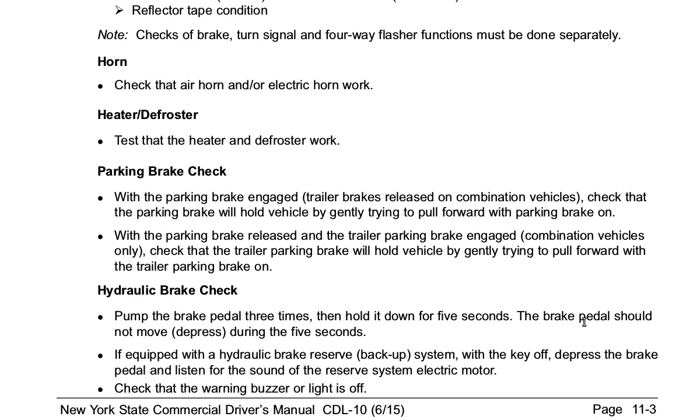Parking brake check. With the parking brake engaged, trailer brakes release on combination vehicles. Check that the parking brake will hold the vehicle by gently trying to pull forward with the parking brake on.